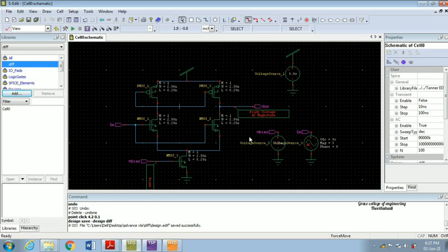Next, we have to analyze the AC analysis curve. For that, I have given the SPICE command as print voltage AC magnitude. We also have to be concerned that while analyzing the AC performance of a circuit, we should give the input in terms of AC. For AC, the magnitude I have given as 5, and VDC I have given as 5 volt.